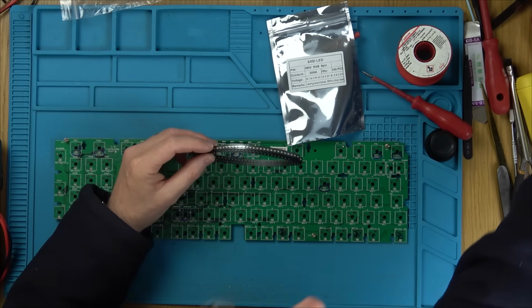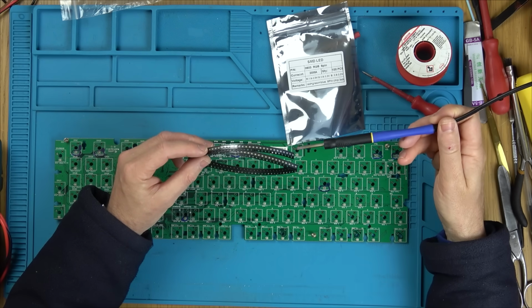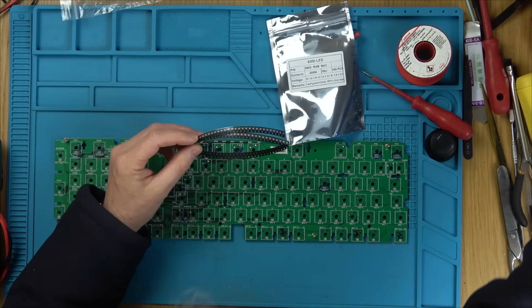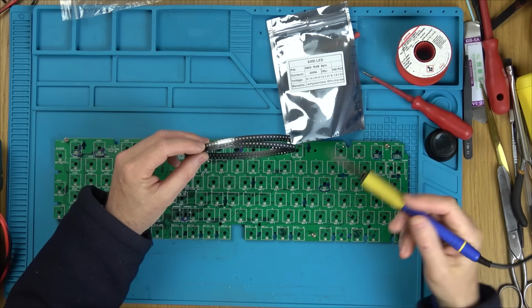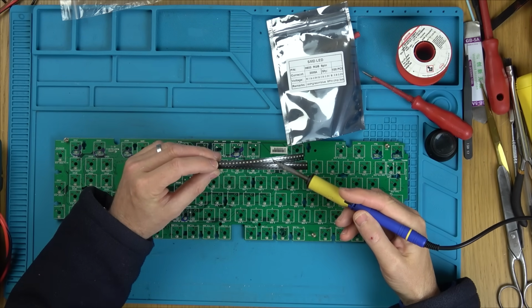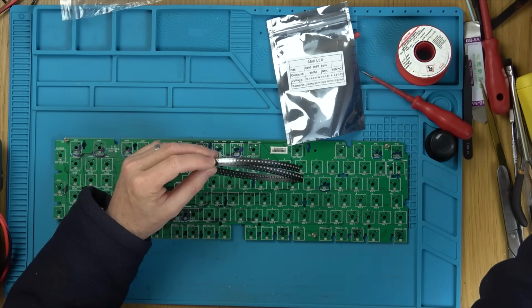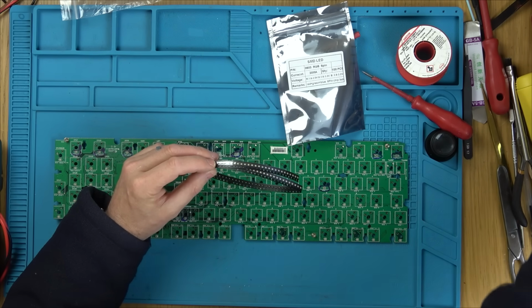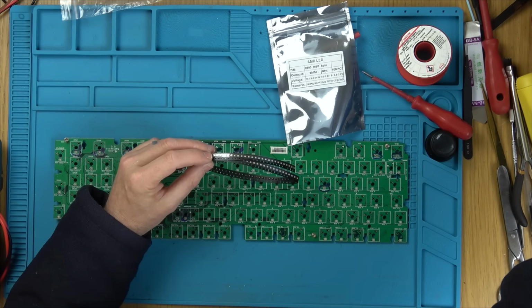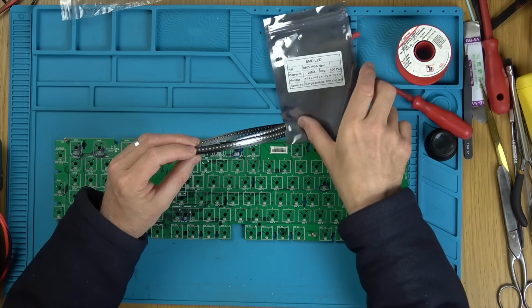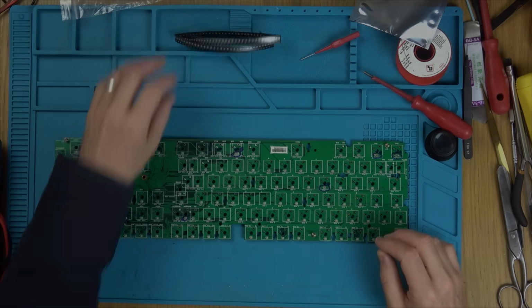I might need to use the micro pencil for this, which is a lot smaller, but that might not put enough heat into the board here. So I'll try it with the normal soldering iron. It's just that the normal soldering iron is near enough as big as the LED itself, but I've got plenty to waste. It doesn't matter, I've got 100 of them. So if I end up burning the first few while I'm experimenting with what's best to use, I don't mind. So I'm going to do this under the microscope.